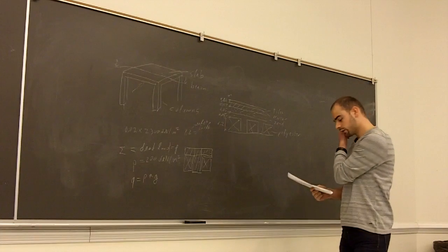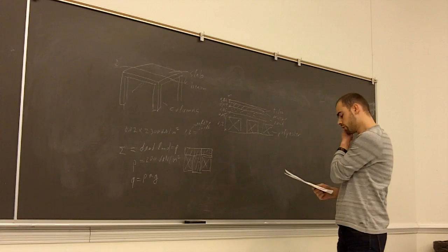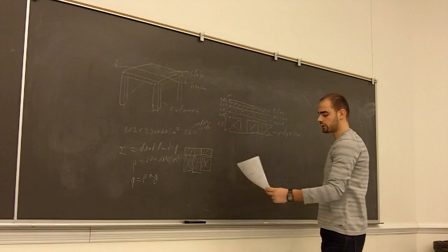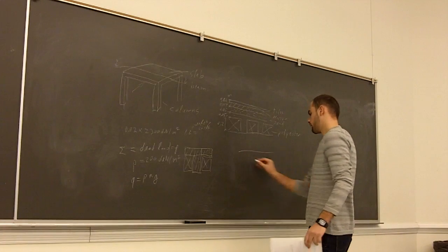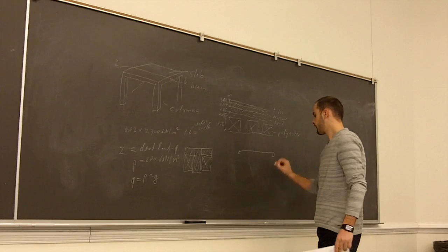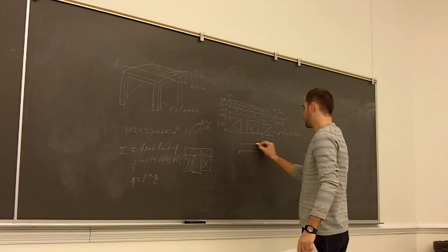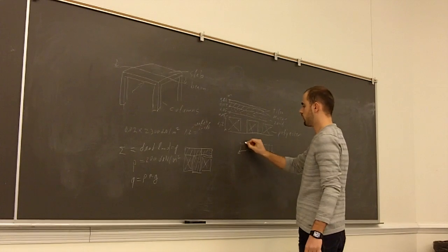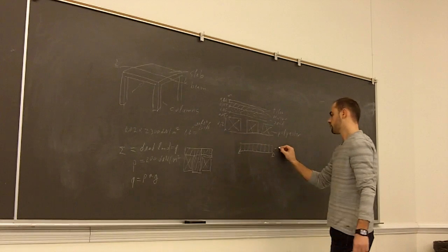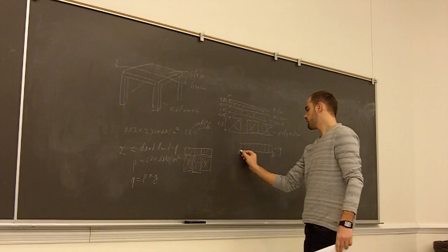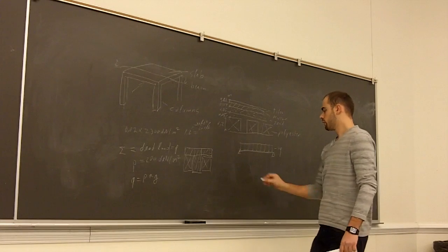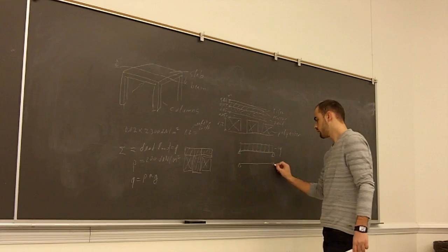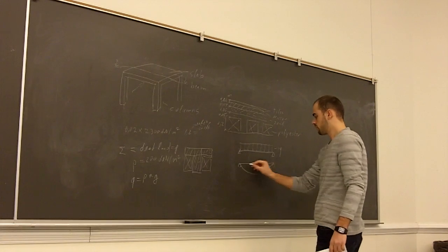After having calculated the load of the slab, we take a calculation scheme for the slab, because this is a T section. The scheme is this. This represents the load, the Q load, and this represents the slab. So if we draw the diagram of the moment, we'll have this.